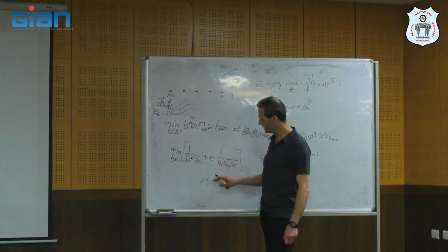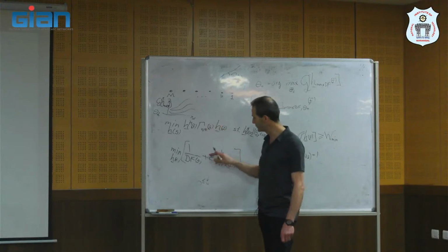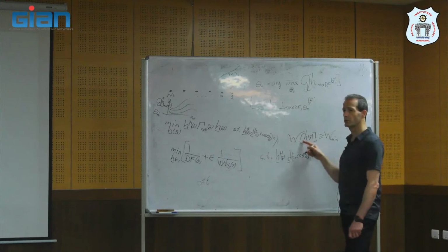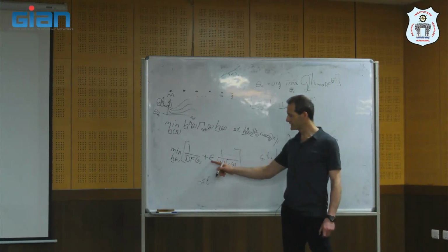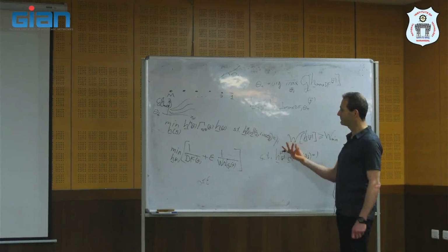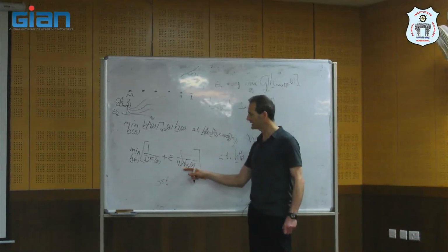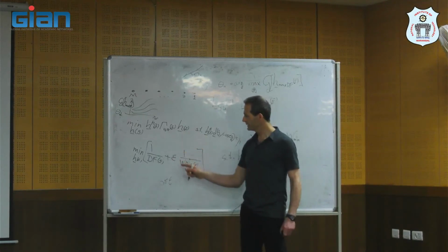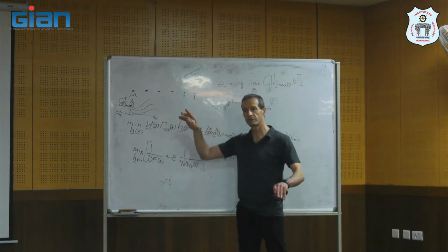If epsilon is larger than 0, the more that I increase it, the more weight I give to this requirement. So it will try more to minimize this. It will increase the white noise gain, but it will decrease the directivity factor.